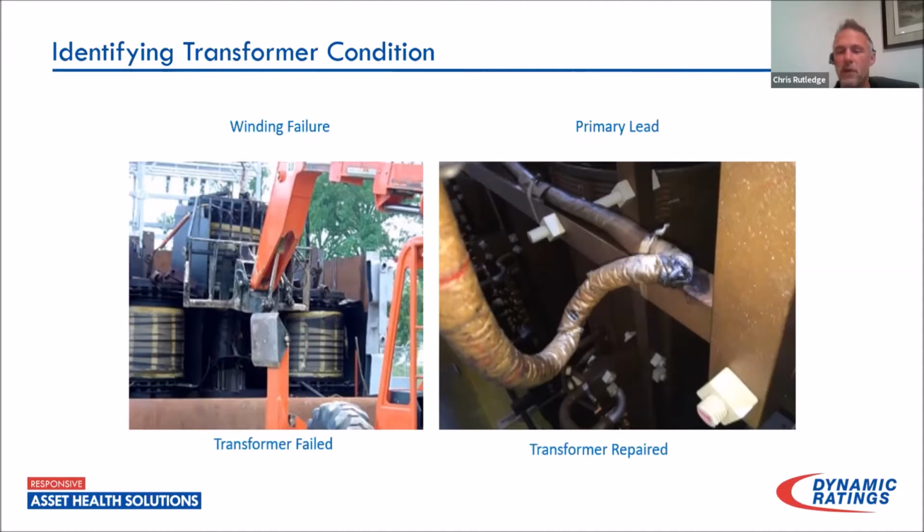It was odd because they were getting ready to take this transformer and replace it. I took a look at the DGA samples, and going by the carbon oxide ratios, I said no, you didn't have a failure. There didn't seem to be enough cellulose breakdown involved, so you need to investigate a little further before you scrap this one. Important to mention, both these units did trip off while in service, and a power factor test was attempted on both of them, and neither one of them would test.